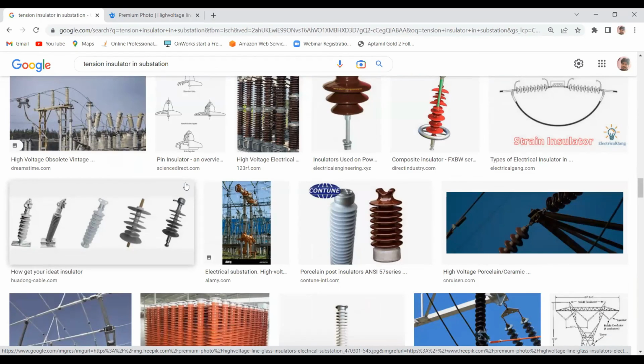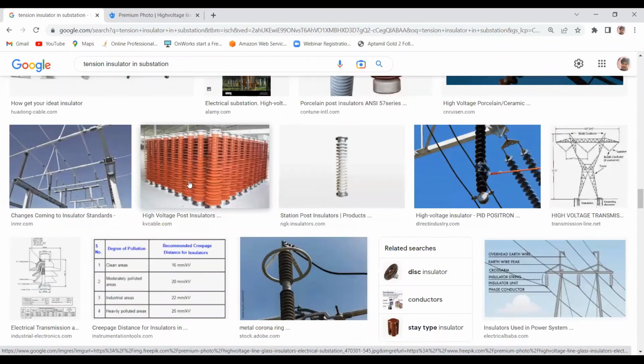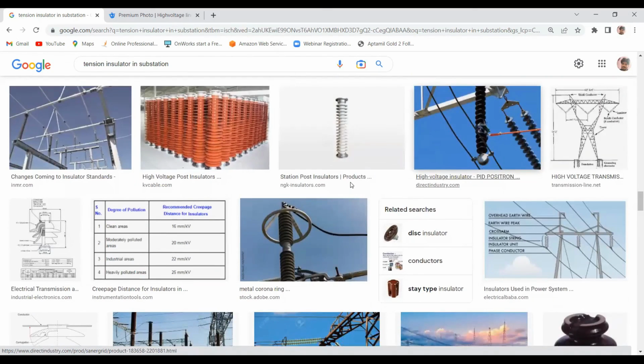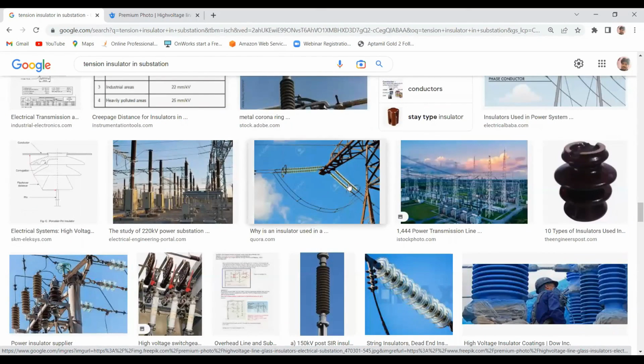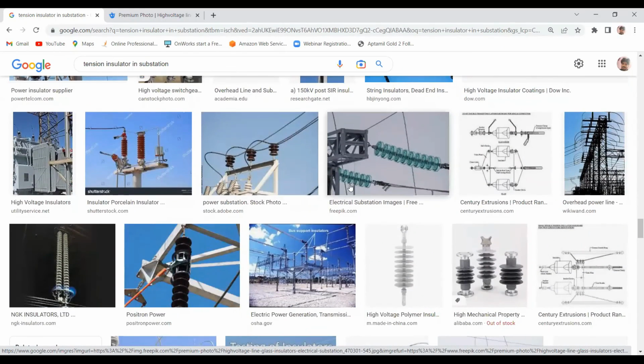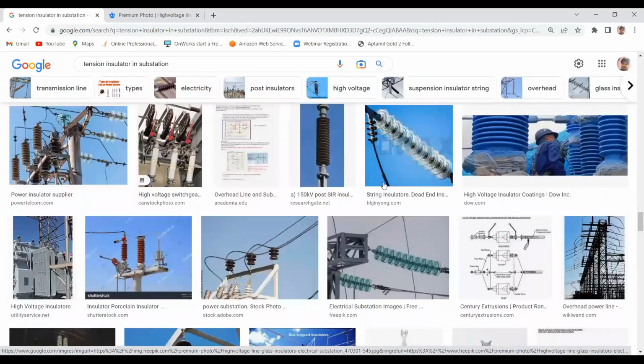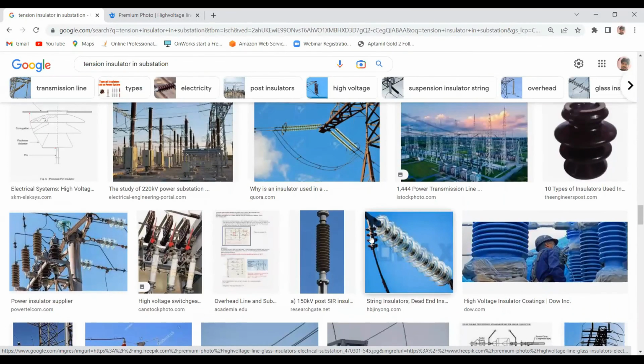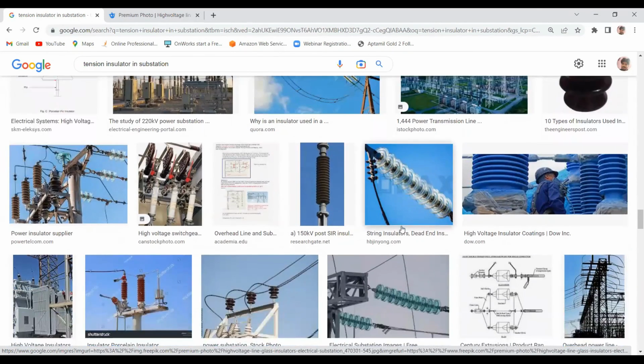At the time of erecting this, we will notice, oh, this clamp will not suit mine. So we have faced this type of issues at the time of commissioning. So it's very important to see the clamps and connectors when you are doing the project. Fine. So you can see here the turnbuckle is there. But at that end, you cannot see the turnbuckle.